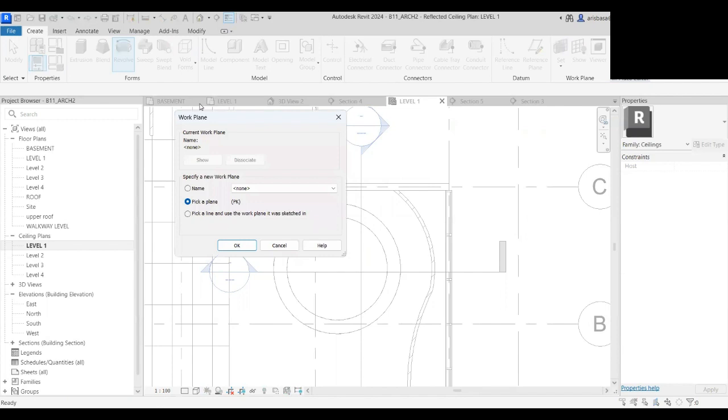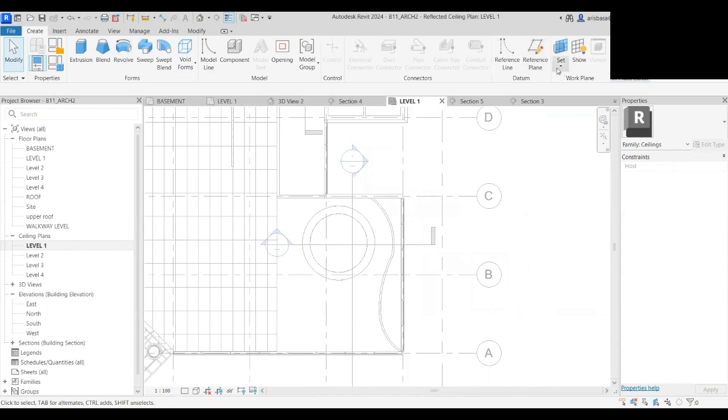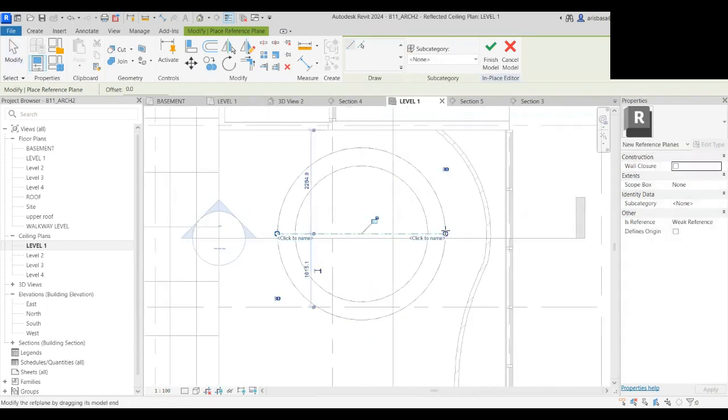We click revolve, okay? Then it will ask for, okay, just watch now. We'll get a plane. We need a plane. It's like a sectional view. So we don't have it yet now. So I'll close this and I'll do that again. We need to create a reference plane, which is from here in the middle, right? Up to there. Okay, we'll name that ceiling, curb ceiling.